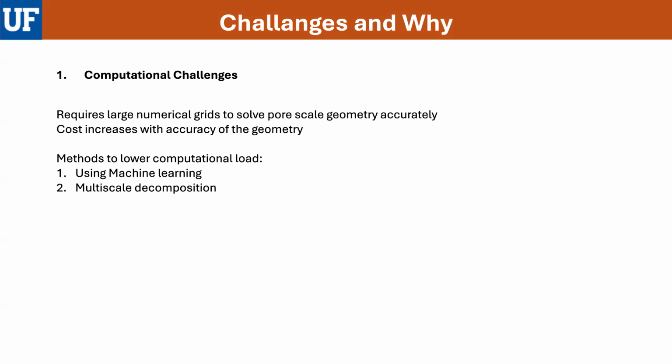In multi-scale decomposition, let's take an example of a physical variable like velocity. It is split into two parts: volume average and local deviation. What is volume average? Volume average captures the global variation with long wavelengths, while local deviation, the second part, captures the smaller fluctuations. Then how is it solved using multi-scale decomposition? We use the tridiagonal matrix algorithm, also called TDMA, to solve it. Going forward,